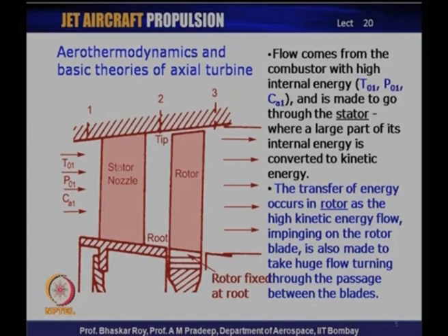So, the rotor of course is the unit which will do the work in the old fashioned concept of a turbine doing work, but we need to create a high velocity jet to impinge on this rotor, as it is done, let us say, for centuries in a water turbine, or as is available to wind turbines. Now, this jet needs to be created artificially inside the actual turbine. It is not available naturally.